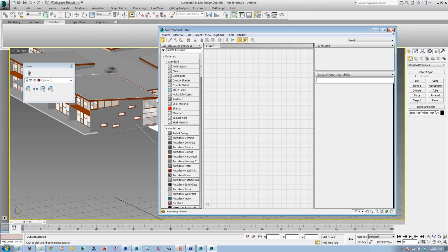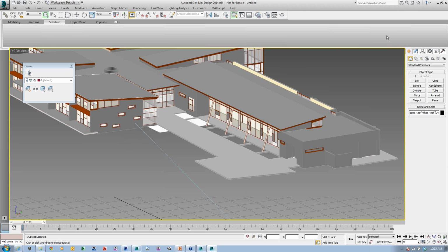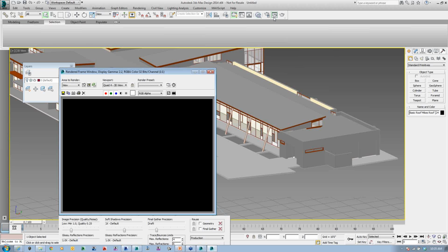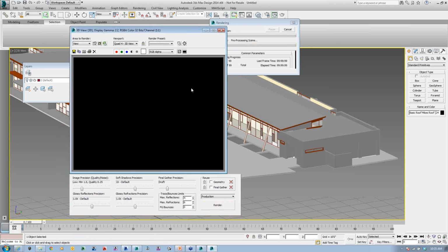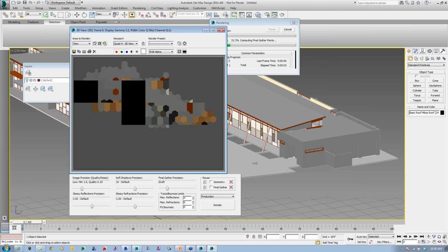Now, did some of your materials come across from your Revit model? And so you have the base materials laid out. Is that correct? Yes, I do. And see if I can do a quick rendering. We won't necessarily get to see all that in here, but I'm going to set it to low quality and have that run through my little window. I always put that on low quality and check that beforehand.